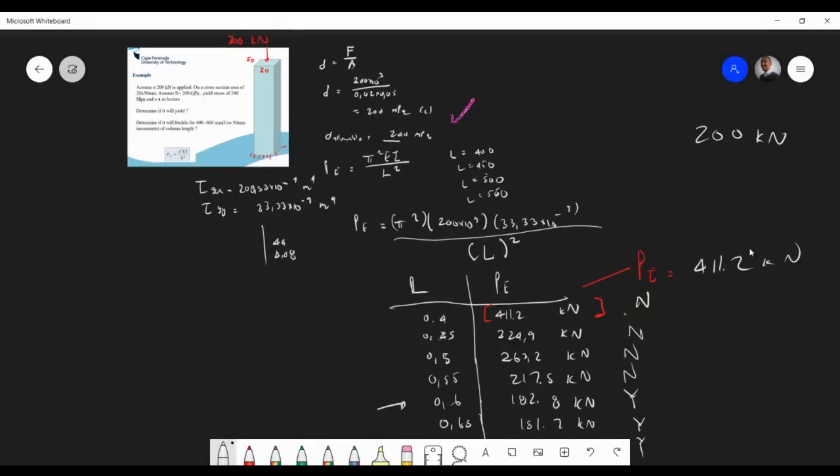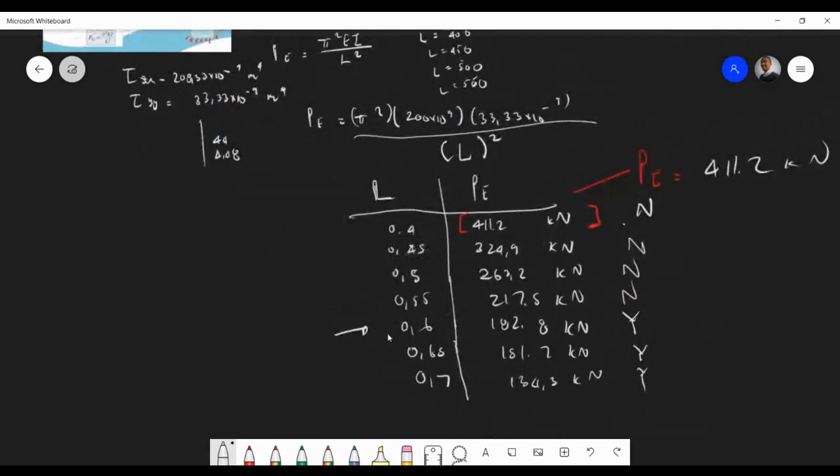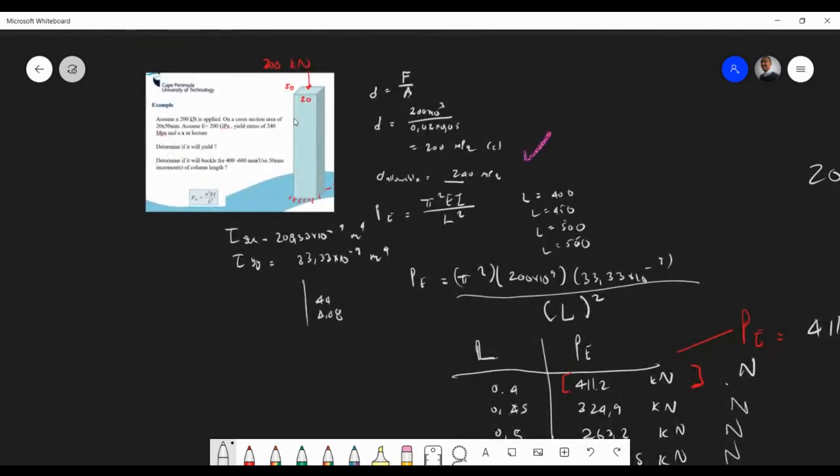It's not like stress or whatever. In fact, when you design this column, we're going to have to use this load here. We know it'll buckle depending on how long our column obviously is. We have to make adjustments so that we find a compromise between the area of the thing. Obviously, there are certain things which are fixed, which we can't actually change and choose. So one has to find a compromise between the two.